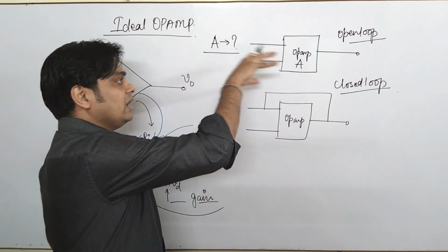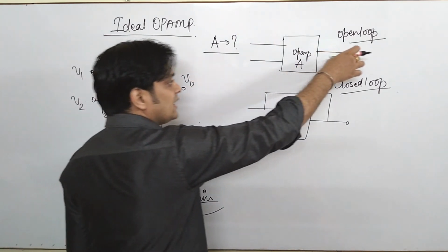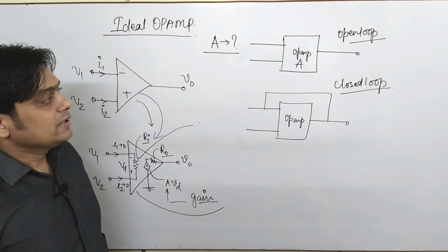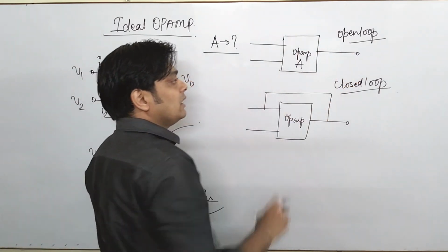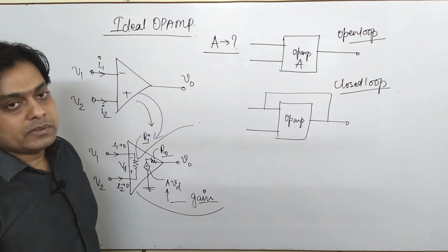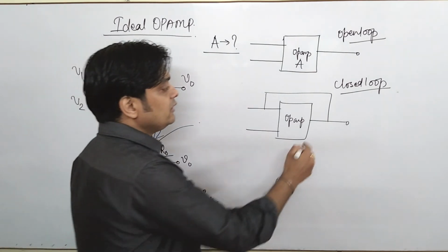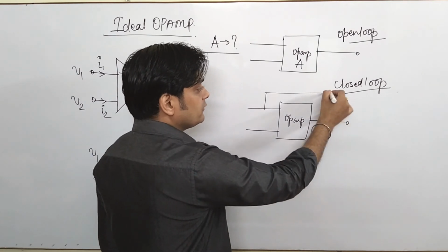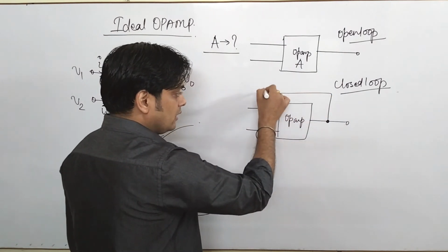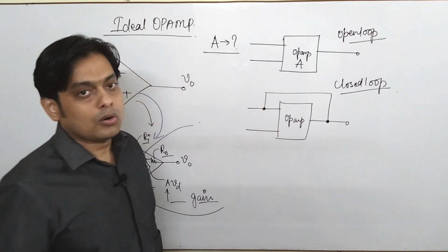Why? Because of this very high gain, various critical conditions are created at the output, because of distortions and harmonics. The output becomes unstable, and at that instant it is very difficult to measure the parameters at the output. That's why a new concept was introduced, known as closed loop. We will take some portion of this output and add or subtract it at the input.